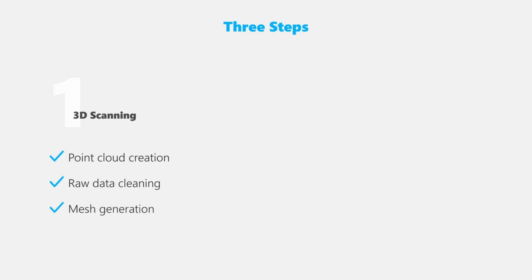The second step is modeling precise geometry in KOMPAS-3D based on the mesh. You can use standard solid, sheet metal, wireframe and surfaces modeling commands for this. The third step involves production using various methods, for example casting, 3D printing or CNC machining. In this course, we'll explore the second step and create the impeller model based on its 3D scan.